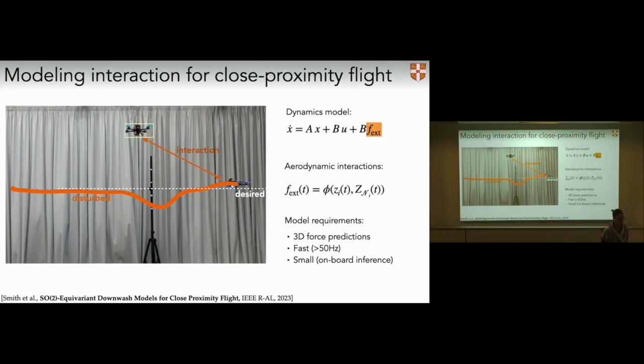And what we now do is we take our interaction model, which I introduced before, because it basically allows us to model what the other nearby robots are doing. And we're simply going to try to learn the parameters of our function phi in a supervised manner. And we can do this in an indoor setup because we can track the robots with ground truth information, and at train time we can actually produce labels for these kinds of systems. So we have a way of training these systems in a supervised manner that is quite precise.